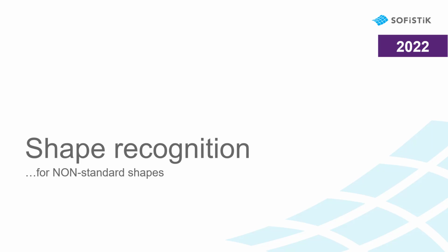Those 99 bars are all treated the same by the software, and our general bending shape sketch is generated for them in real time by the program. This has two major disadvantages. The generation is complex and performance intensive, and the sketches can become illegible in certain situations. That is why we have improved the bending shape recognition. The user now has the option of defining his own standard bending shape codes and can then assign the corresponding bending shape family to them.